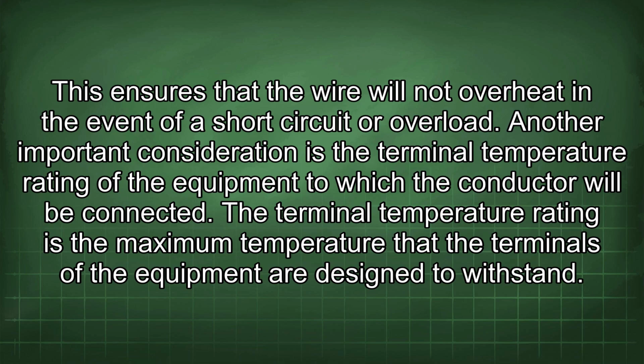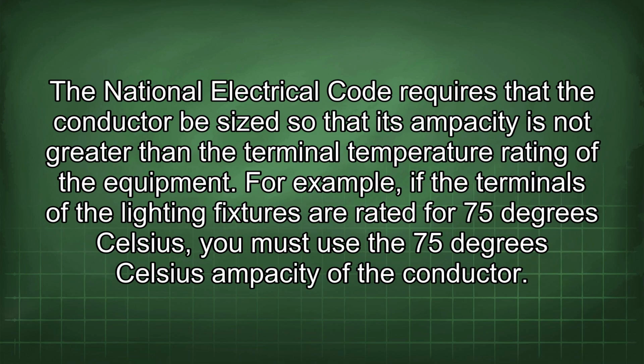Another important consideration is the terminal temperature rating of the equipment to which the conductor will be connected. The terminal temperature rating is the maximum temperature that the terminals of the equipment are designed to withstand. The National Electrical Code requires that the conductor be sized so that its ampacity is not greater than the terminal temperature rating of the equipment.